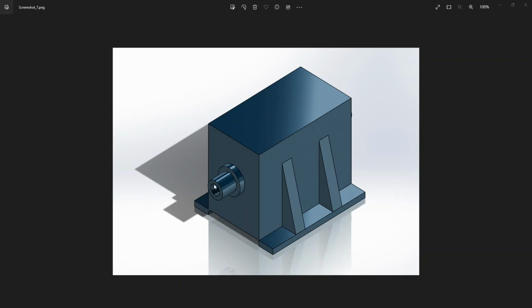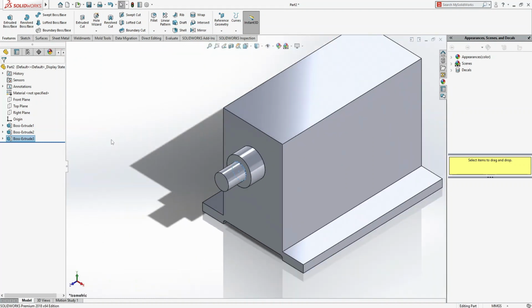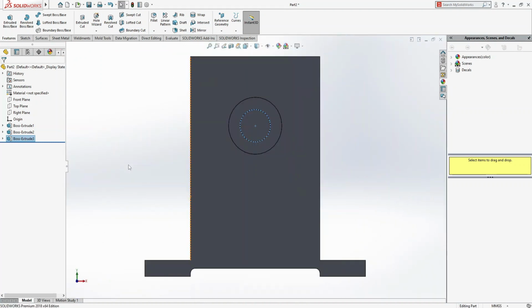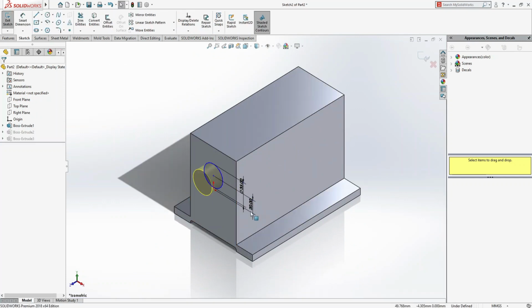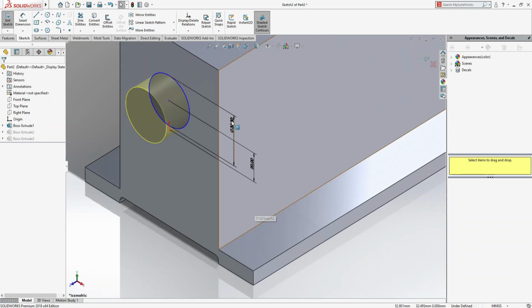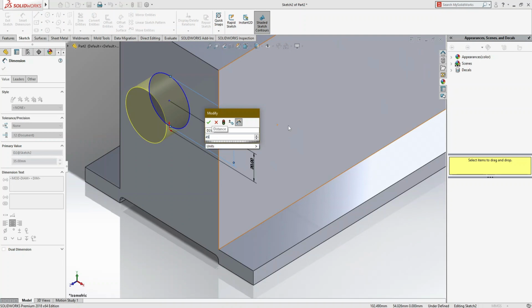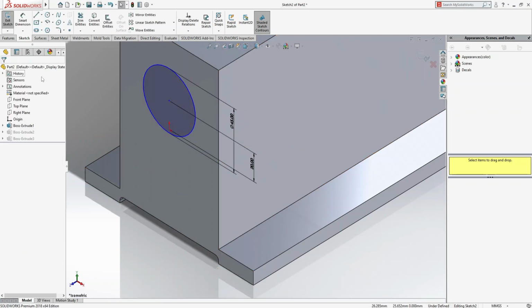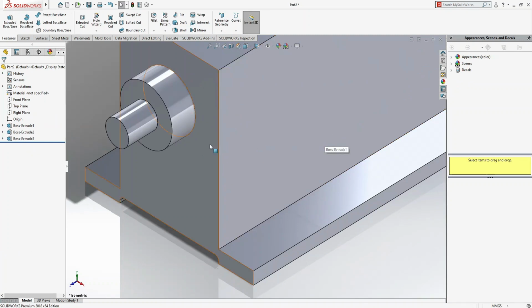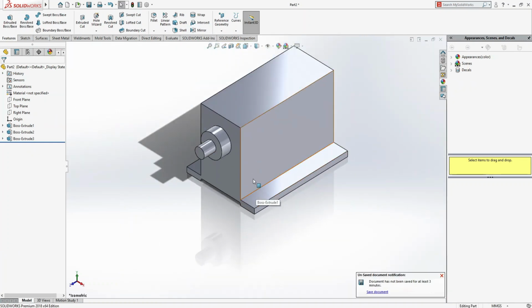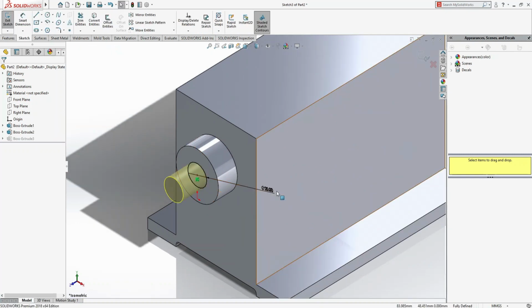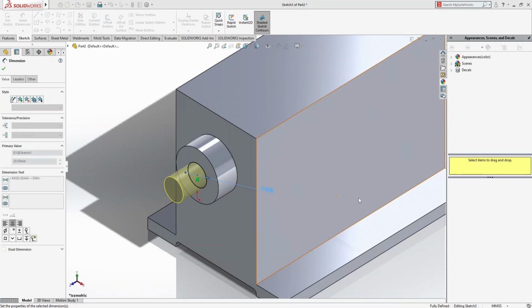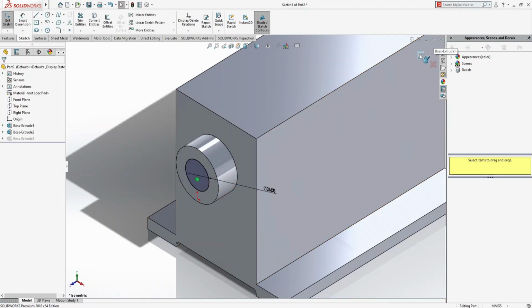Now next there is a hole. So okay, one more thing. Ctrl 7, this extrude, edit sketch. Let's change its 35, let's make it 45 mm. I am increasing its diameter. Okay, 45 mm, Ctrl 7, and one more thing, now we need to change this also, 20, let's make it 25 mm, and okay.